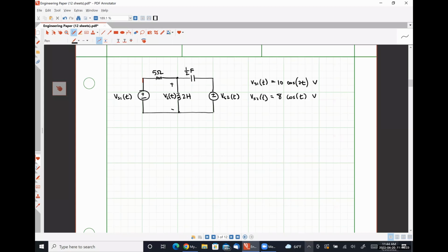So we can't look at this circuit all in one go because we wouldn't know whether to treat the inductor as a, let's see, so 2 times 2, so a J4 ohm impedance or a J2 ohm impedance, right? Because it actually exhibits both of them simultaneously. Similarly, our capacitor is going to exhibit a negative J impedance and a negative 2J impedance, depending on which frequency we're looking at.